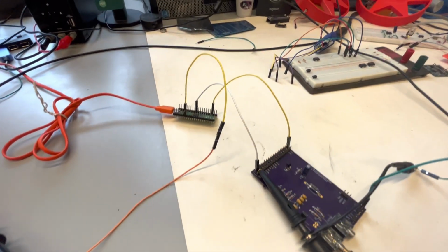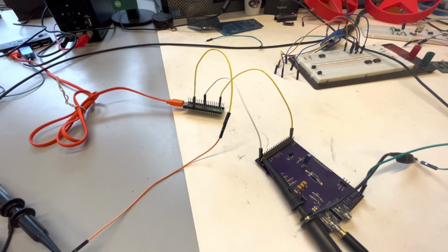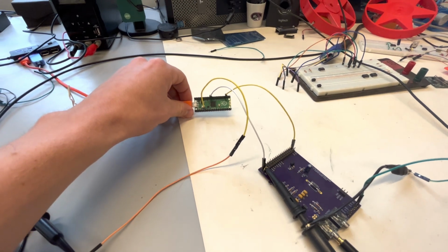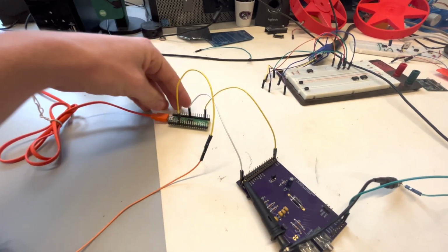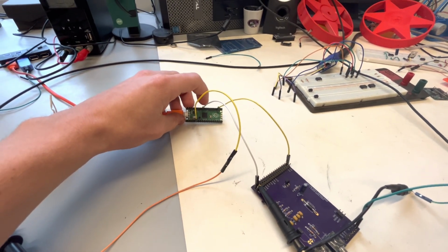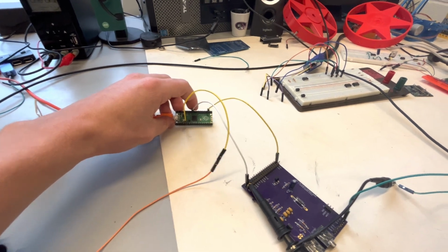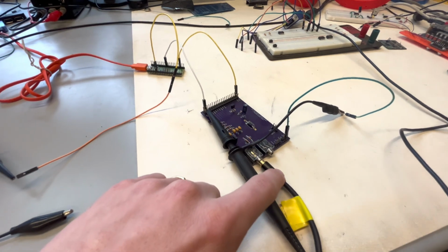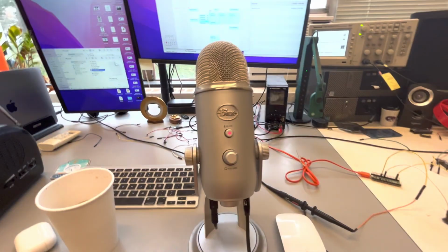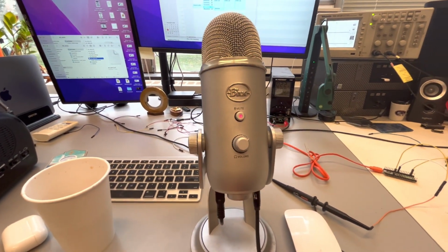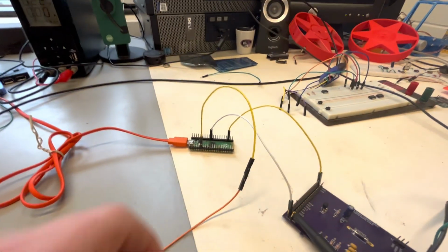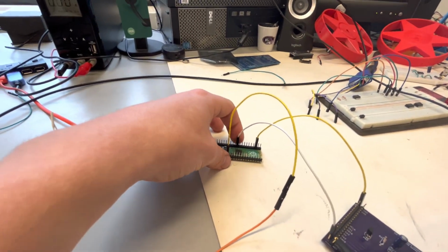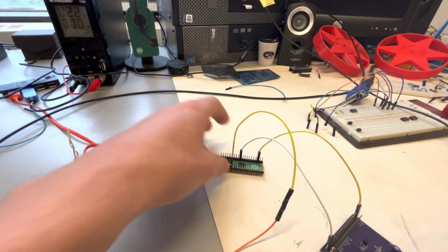This is a demonstration of audio transmission via AM radio using a Raspberry Pi Pico. Plugged into analog input 0 here of the Pico is this jumper. This jumper communicates through a high-pass filter into this aux cable, which is plugged into this microphone. So as I speak into this microphone, the analog input 0 here will be used to sample my voice at